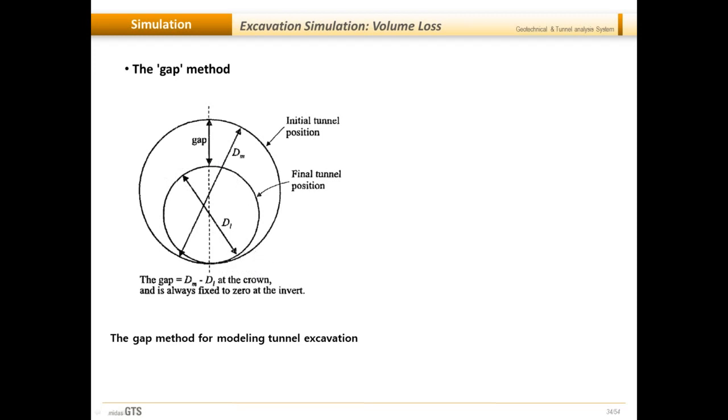There are in-plane and out-of-plane effects that we try to replicate, and this type of approach is applied for a 2D analysis, where there are limitations that you cannot apply a 3D analysis. So in 2D analysis, you try to simulate the effect of 3D or out-of-plane effects using this analogy. And depending upon what construction methodology you are using, the void size and the initial position of the excavation would vary.